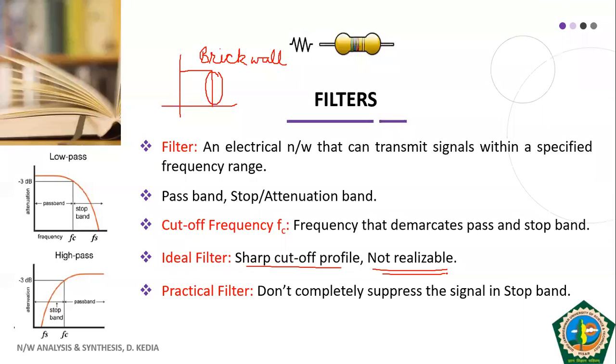Okay, so what is the solution then? Practically, the kind of filter that we are able to design, that filter is called as practical filter. Now what will happen in practical filter? In practical filter, we will not have sharp cutoff profile. Means your cutoff profile will not be sharp like this, it will be gradual like this.